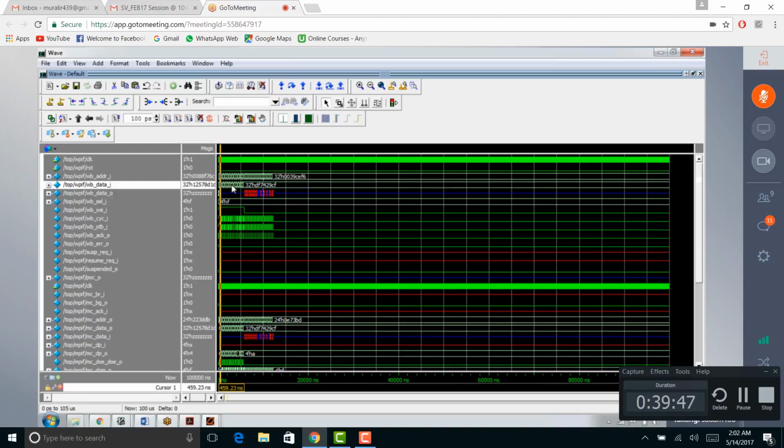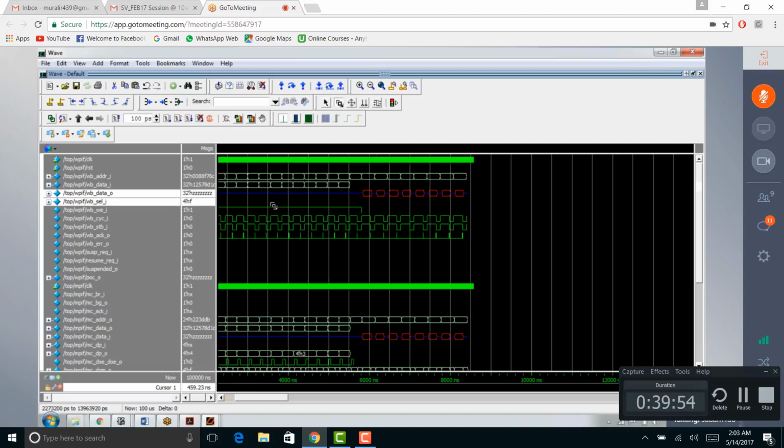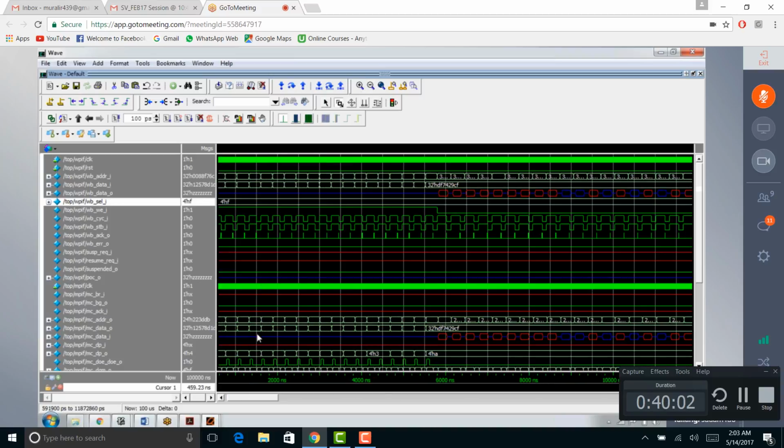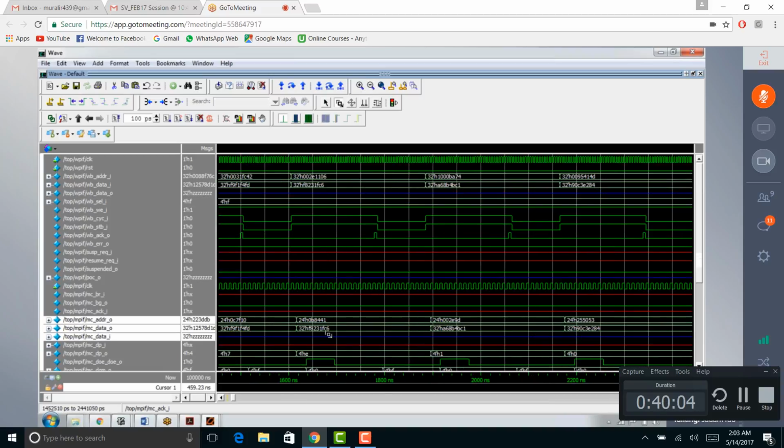So again, same thing, we are writing here, we are reading back here. There's some issue with the read data. It's a known issue, we still haven't debugged it, but we'll check it and let you know. It doesn't give the data properly. One thing you can notice is, writes are happening. Whatever data you write, they are reaching here. You're writing to this value, F8, 2, 3, 1F, 1FC6, it is happening. The same thing you can see, but the reads don't happen properly.